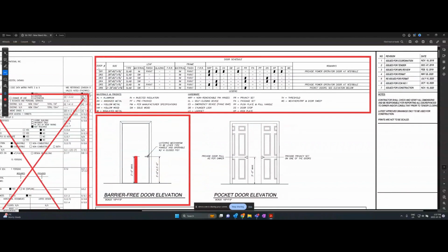Which door types, again, this is your door number here. And then you have to find in the drawings how many there are. This is the sizes. So I know this one here is a DR6, 2 doors. So it must be a pair of doors. 38 by 82 by 1 3/4 slabs. Material is going to be an SW. So the leaf again is solid wood.